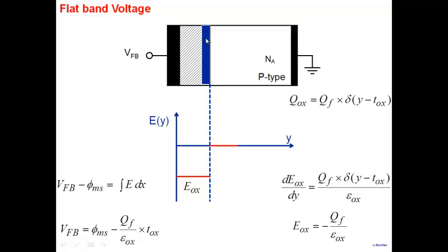So earlier this one was inducing charge here, right? Next to it, it was creating negative charge here and was causing a band bending. And we had to remove that band bending by applying a voltage here. When you take this particular charge and put it here, where does it induce charge? It induces in the metal itself. It doesn't do anything here. So it doesn't have any effect.